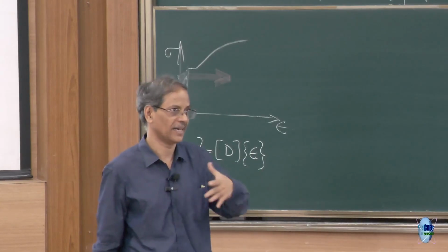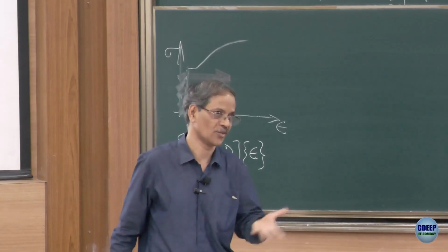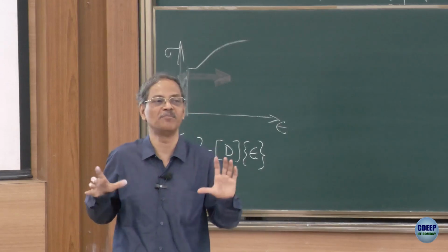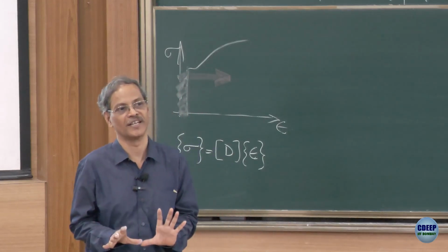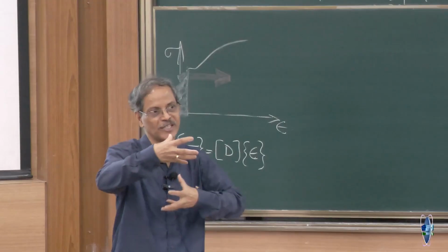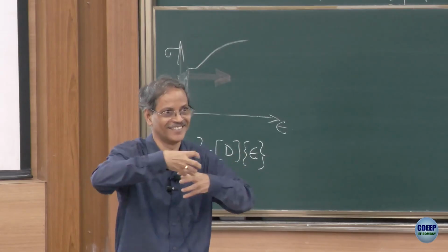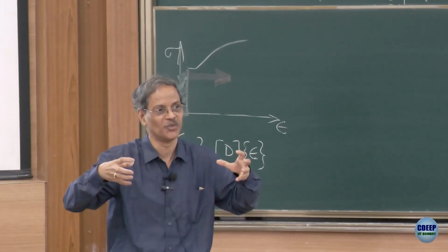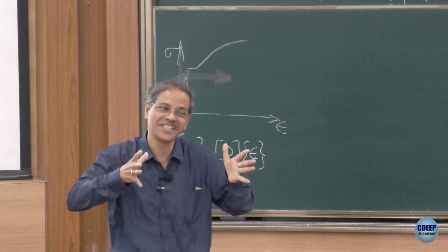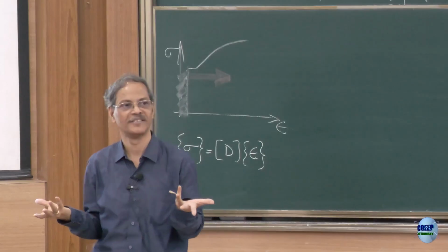Which means, in practice, as you have studied in solid mechanics, you cannot cause a normal stress without also at the same time causing shear strain. In practice, normal stresses and strains mean you are only stretching it, scaling a material up or down. You cannot achieve only that without also distorting the shape, because the material is anisotropic.